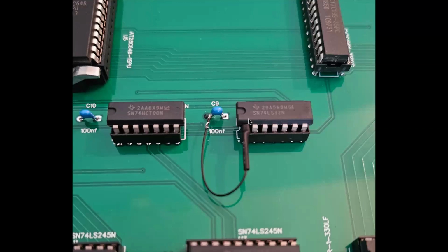So what I did was similar to the backplane board fix I did: I bent out this pin for the OR chip and I wire wrapped that pin and put some heat shrink tubing on there and just grounded that wire